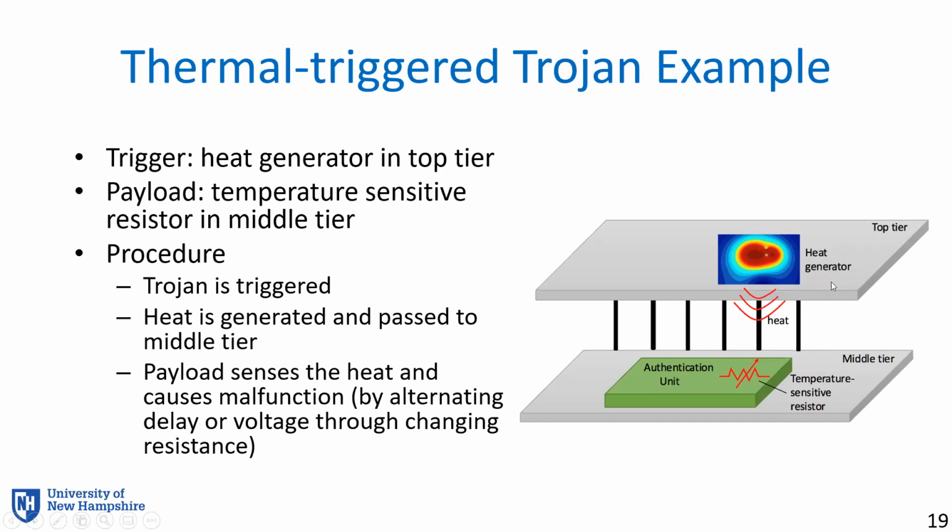If the 3D circuits have a relaxed noise margin for reliability purposes or other functional purposes, then this relaxed noise margin, or guard band on the temperature variation, will lead the thermal triggered Trojan to go undetected, or not have a high detection rate.